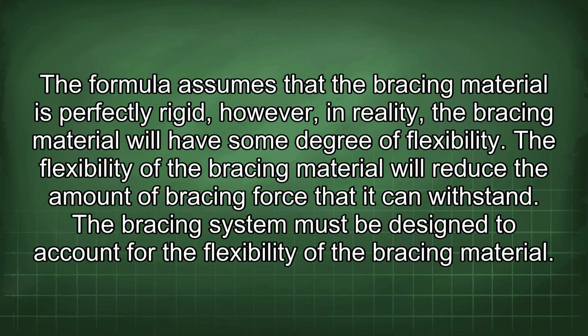The formula assumes that the bracing material is perfectly rigid. However, in reality, the bracing material will have some degree of flexibility. The flexibility of the bracing material will reduce the amount of bracing force that it can withstand. The bracing system must be designed to account for the flexibility of the bracing material.